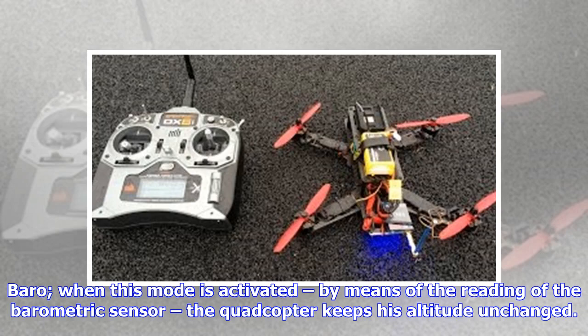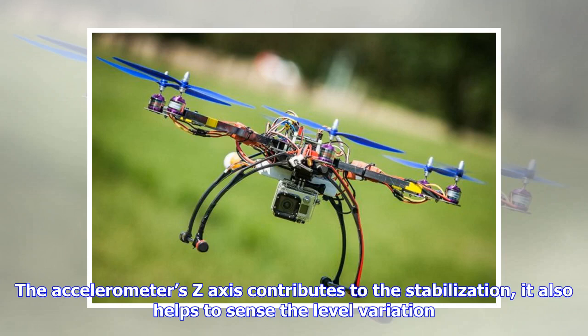Baro. When this mode is activated by means of the reading of the barometric sensor, the quadcopter keeps its altitude unchanged. The accelerometer's Z-axis contributes to the stabilization. It also helps to sense the level variation.